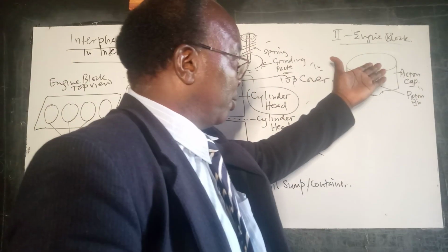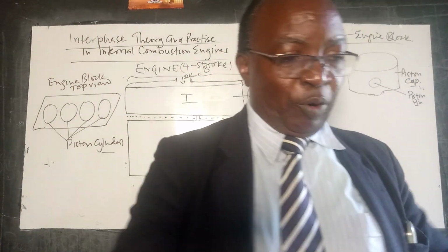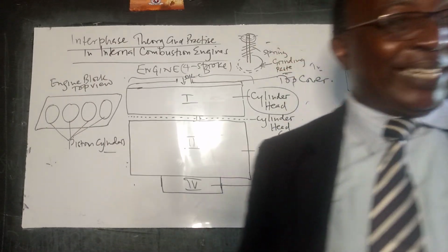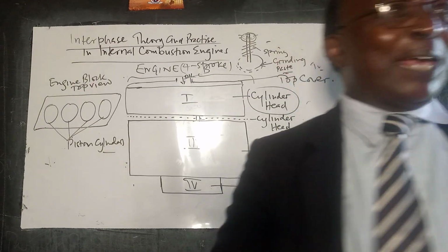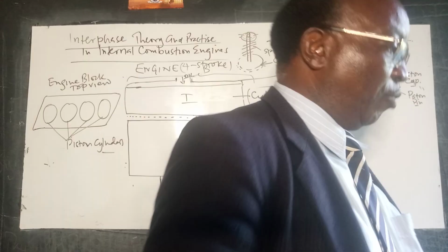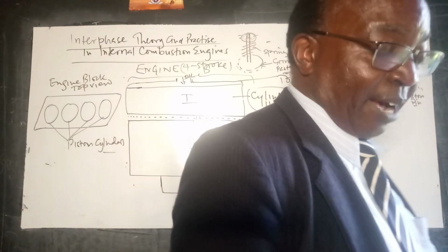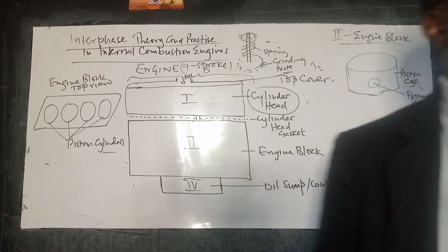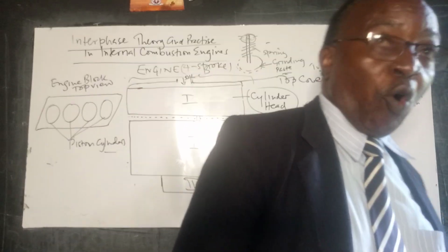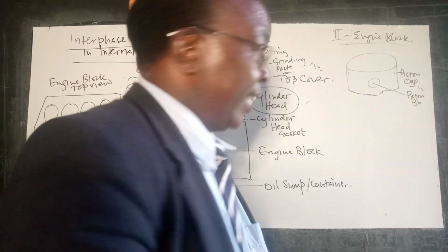Now, there are some of those cups which, if you look, you'll see grooves there. Some of them have grooves that have to do with turbulence, in terms of trying to get effective mixing. There are all types of designs. They vary with different machines, but you see some form of grooves there. Some of them have signs to indicate which particular piston should be put in which particular hole in the engine block, showing you the firing order and so forth.